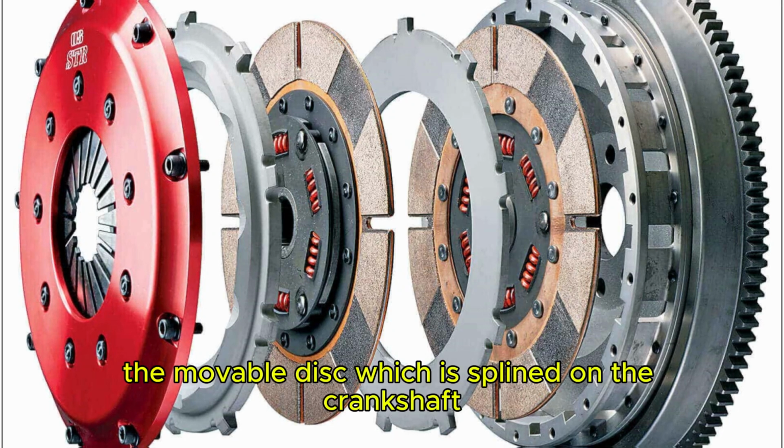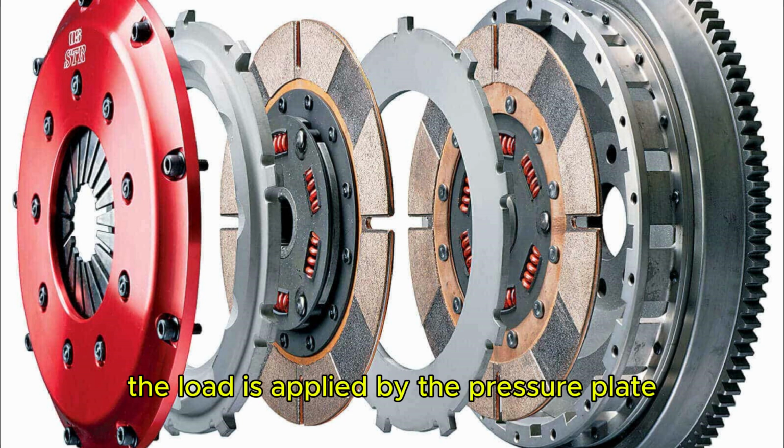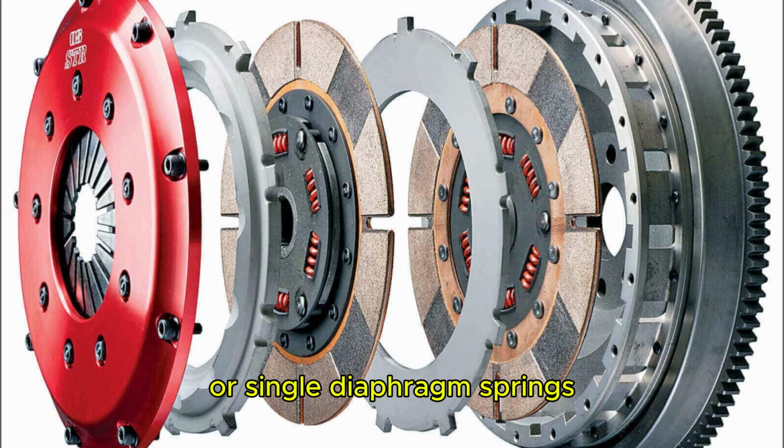The movable disc, which is splined on the crankshaft, moves back and forth with the aid of the clutch pedal. The load is applied by the pressure plate, which is connected to multiple helical springs or single diaphragm springs.